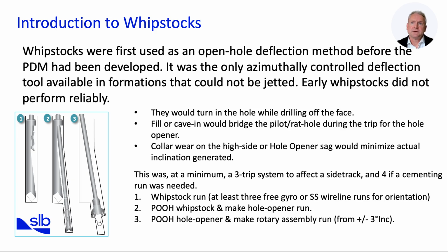Today, whipstocks have made a comeback. One-trip systems enable us to hang the whipstock on the bottom of the drilling assembly. This enables us to set the whipstock in place and drill out in one go. In mature fields where old wells are being repurposed to target unswept reserves, this is very beneficial.